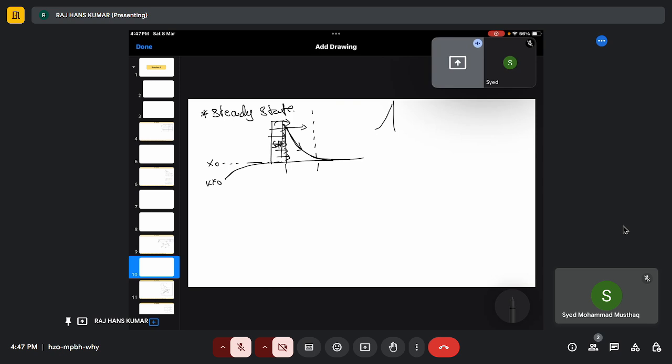Now, again, the solute atoms that have been diffusing down this concentration gradient, or away from the interface, must be balanced by the solute atoms that have been rejected. Right. Now, how do we write the flux of atoms that has been coming down this concentration hill? It will be equal to minus D dou C by dou x, or dou Cl by dou x, inside the liquid.